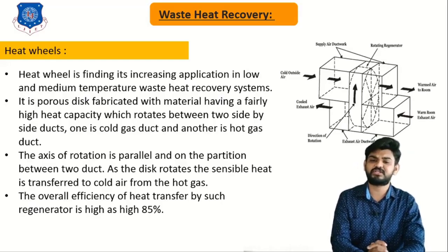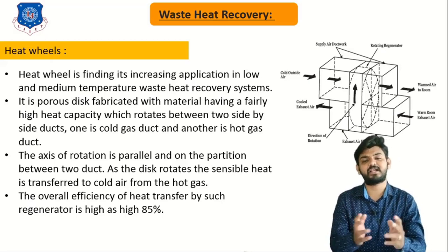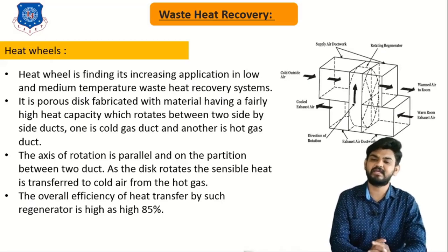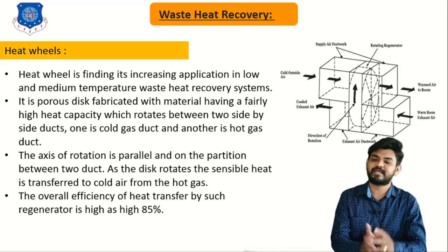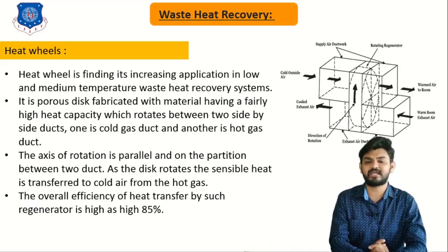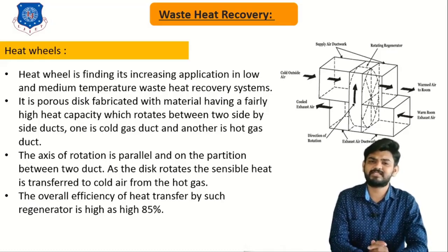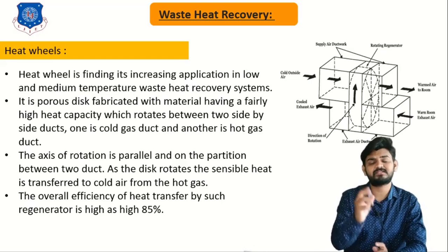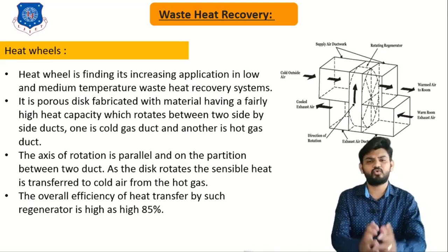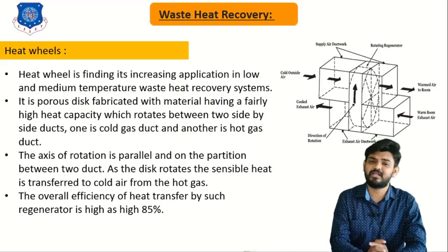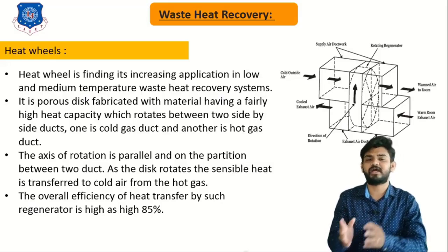It is a porous disc fabricated with material having a fairly high heat capacity, which rotates between two side-by-side ducts. One is the cold gas duct and on the other side is the hot gas duct. So basically you can see in the image the diagram for the heat wheel. It is made up of two different ducts that are utilized for the hot fluid and for the cold